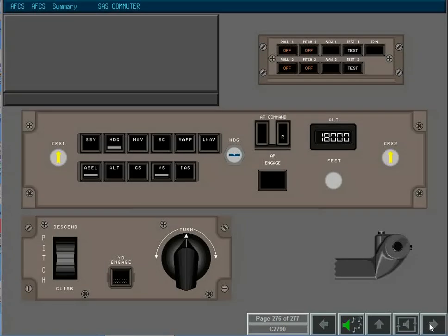The autopilot is automatically disengaged if there is a data fault from both AHRS, the flight control lock is on, or the stick shaker is activated. The autopilot automatically disengages if a failure is detected in the pitch or roll channels that cannot be localized to a specific channel. Yaw channel failures do not lead to autopilot disengagement.